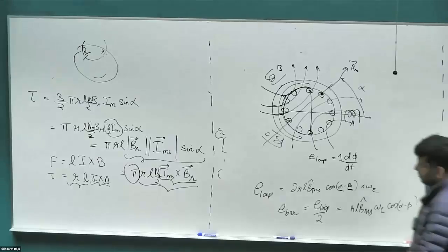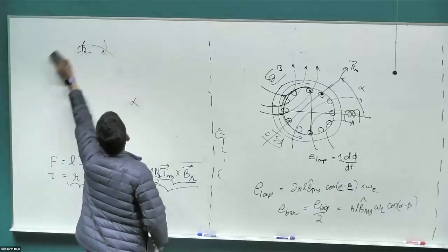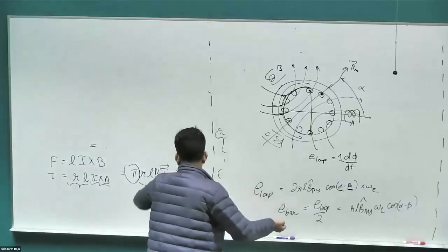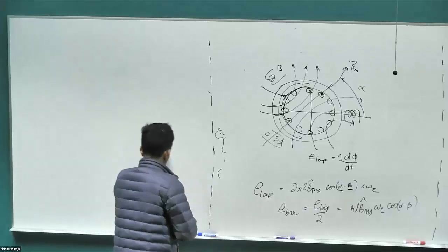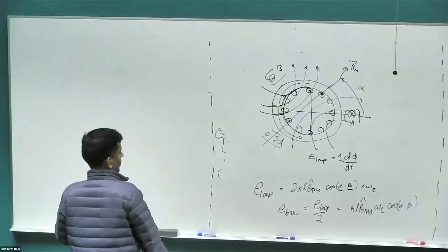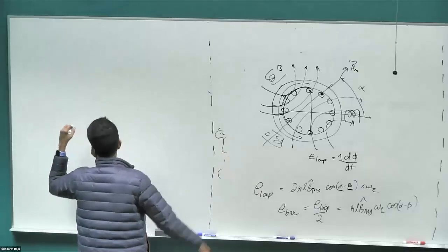So far we have a bunch of rotor bars, except the resistance is infinite. But of course, these are copper bars. The resistance is extremely tiny, so there's really huge amounts of current that flows in the bar. And so we are going to visualize this, whatever the diagram that I have there.